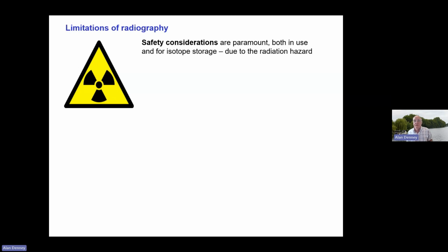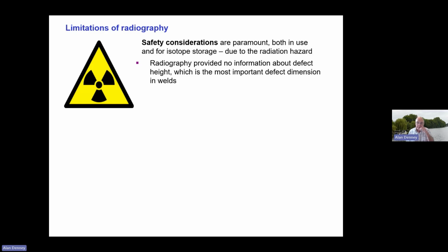So, limitations of radiography. Well, I've already mentioned the safety considerations. They're paramount, both in use and for isotope storage, due to the radiation hazard. There's only a radiation hazard with X-rays when the thing is on, but with isotopes, gamma rays, it's an issue at all times.